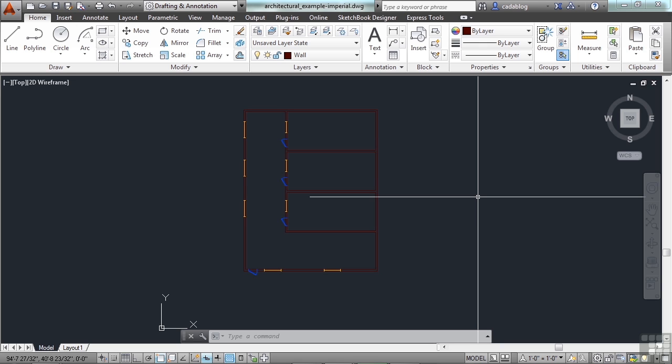Every object can be either assigned its properties individually or it can be assigned by layer. The 3 main display properties an object can be set to are color, line weight, and line type. Each layer can have all of these properties set as well, and transparency is another one if you use that. It's a good practice to keep all of your objects set to by layer. That allows you to control them in your viewports. Viewports are windows in paper space that look at model space.